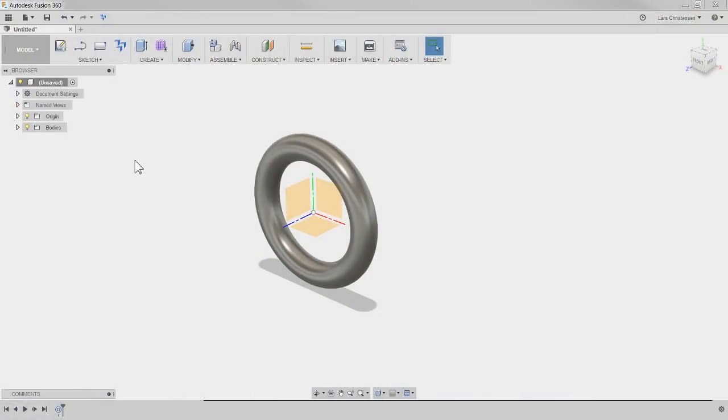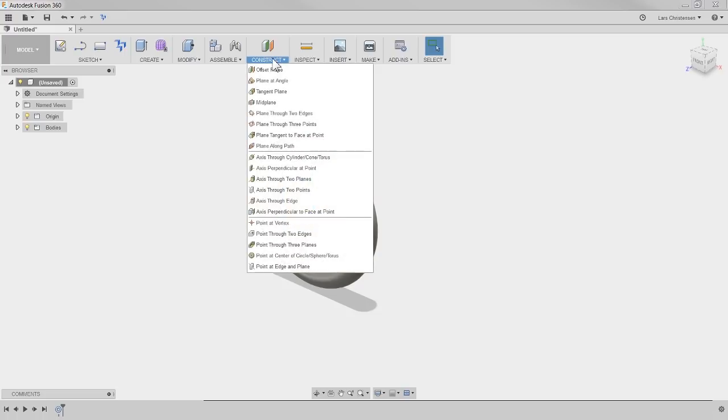All right, so let's move on here now. So like I said before, we either sketch on a face or a plane. Now we still really don't have a plane to sketch on here, and I think what I want to create is that connection rod between the locking mechanism and the handle here. A tool that you should get familiar with is the offset plane up here. So we have these 3 planes by default, but if you hit the drop down, you will see we get an option in here to create different types of planes.